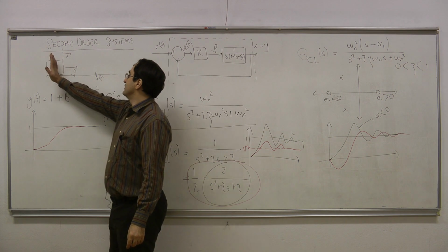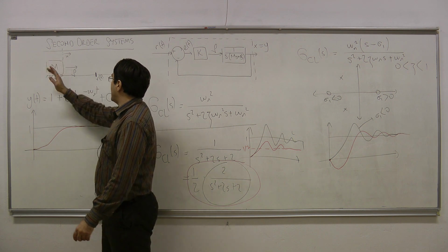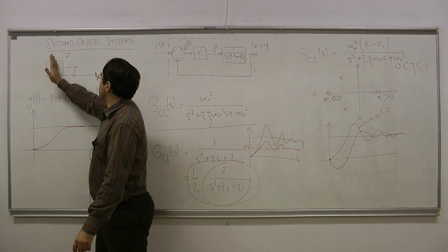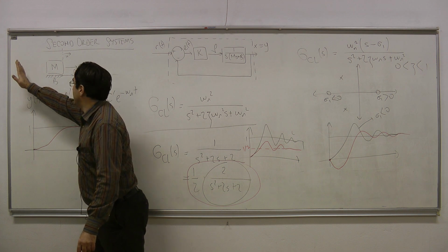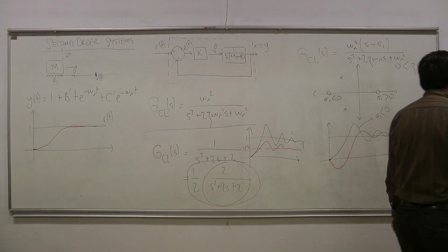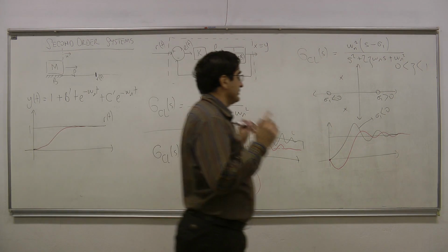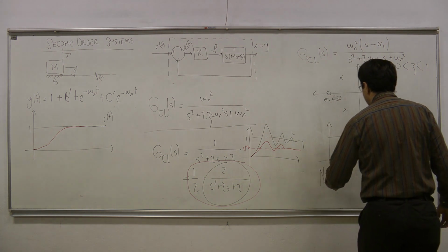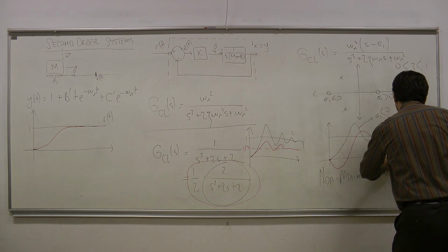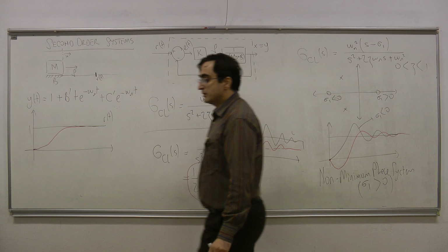What that means is that if my system was like that, I want to bring the mass to here, but when I run my feedback system, the mass would first start going to the left, and then it would come back and converge to the desired value. Such systems are really difficult to control. They are called non-minimum phase systems. You don't really have to understand the meaning of the name here, but they are called non-minimum phase systems. Okay? This is the case when sigma 1 is strictly larger than 0.